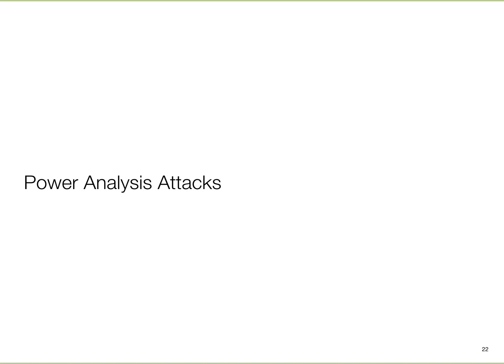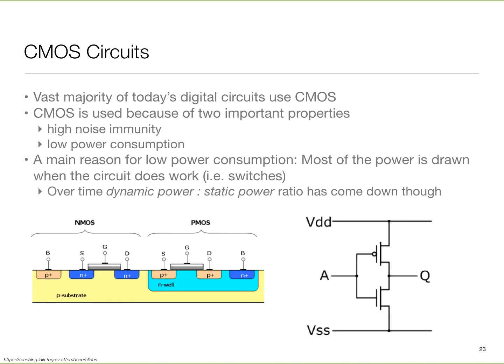I want to talk specifically about power analysis attacks because they have been the easiest one to study in academic settings, and therefore are the most mature of the lot. So at its heart it is about the fact that circuits consume power, and the power they consume is somehow related to what those circuits are doing or the operation they are performing.